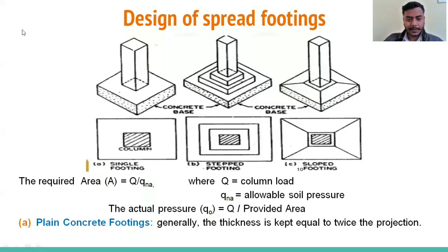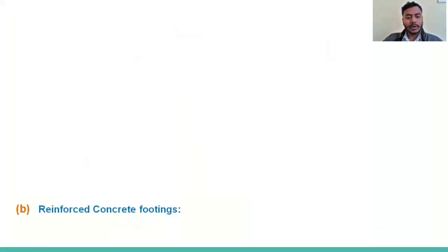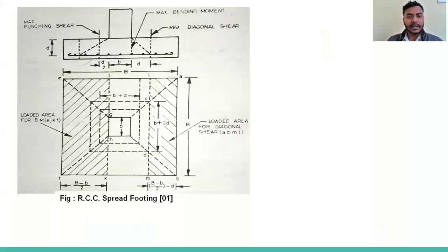So now we can go for next. Okay, the second one, that is reinforced concrete footing. We design a reinforced concrete footing when the bearing capacity of soil is not enough, or when the loads coming are higher. Due to the higher load, higher pressure will develop at the base, so the concrete structure we are designing will not resist the maximum bending moment that develops at the face of the footing, and the diagonal shear and punching shear.